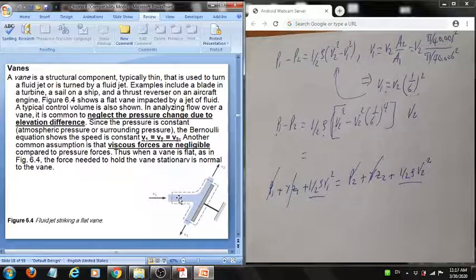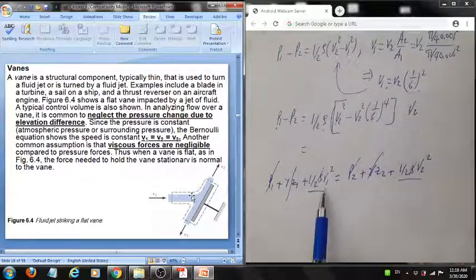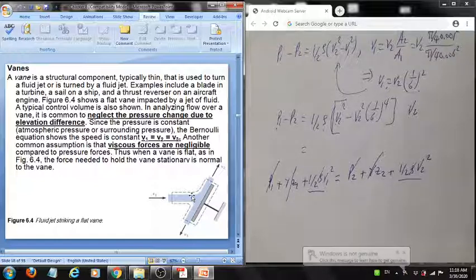And also we typically assume that the density variation is insignificant, that the fluid or flow is incompressible, so we end up with rho canceling out, and we end up with V1 equal V2. Same thing we did for V1 and V2, we can do for V1 and V3 and show that V1 equals V3.